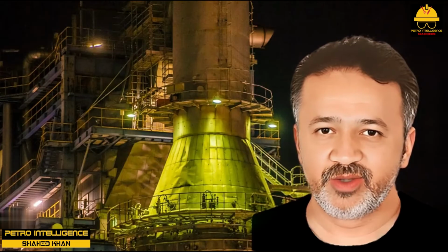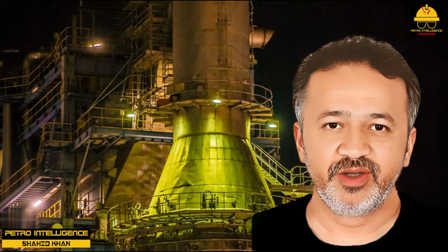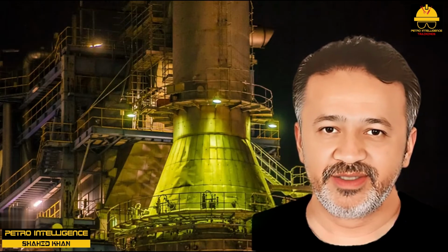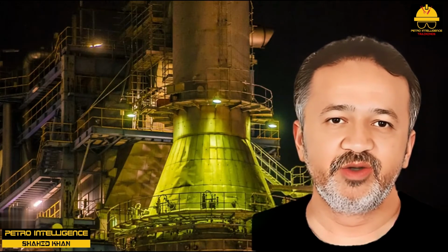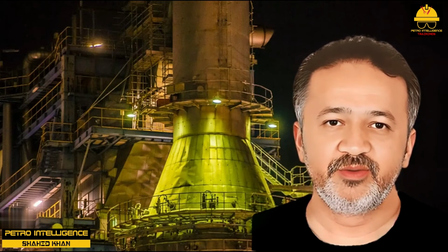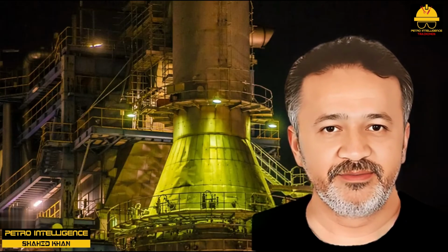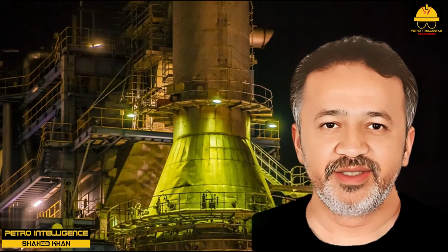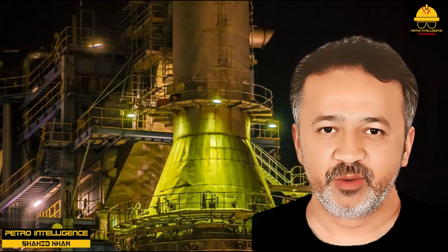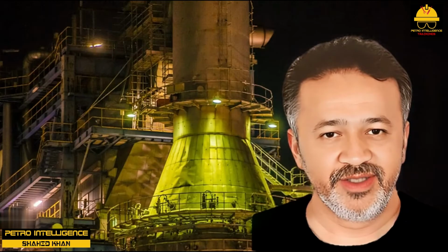This correct percent O2 in the firebox can be determined only by experimenting with the fired heater, furnace, or boiler in the field. This firebox O2 will also vary for any given piece of fired equipment depending on a variety of factors, including mechanical integrity and firing rate. In reality, it is not the firebox oxygen content that we are looking for so much as the correct combustion air rate for proper operation.